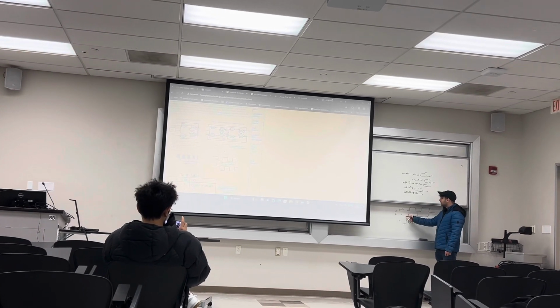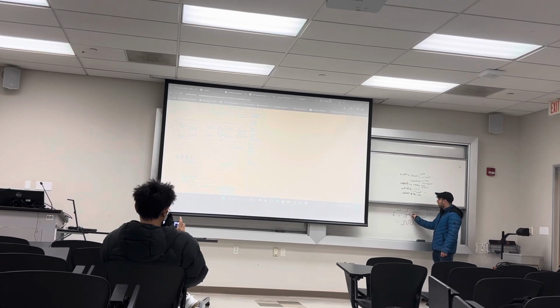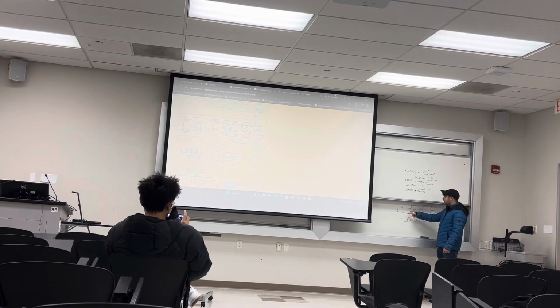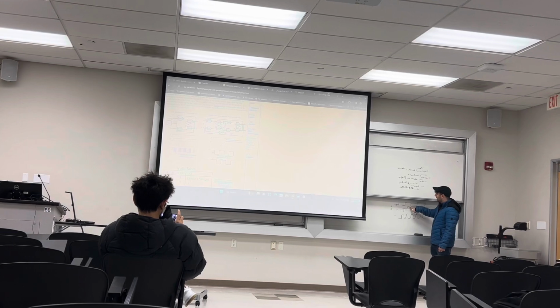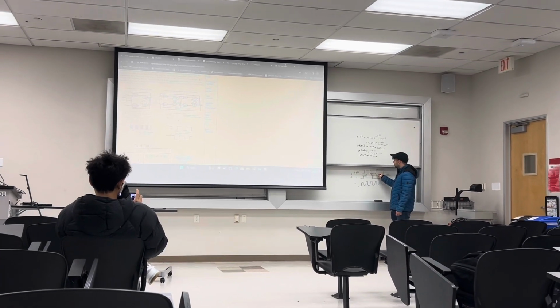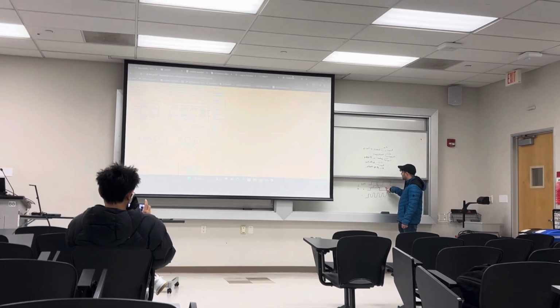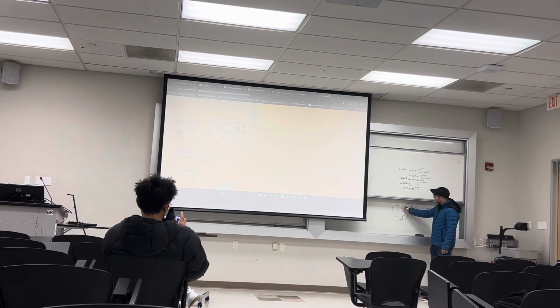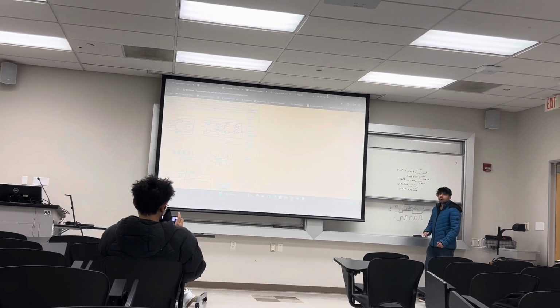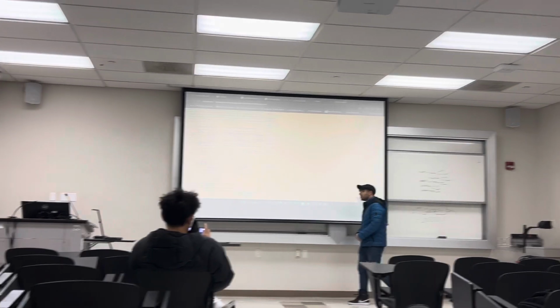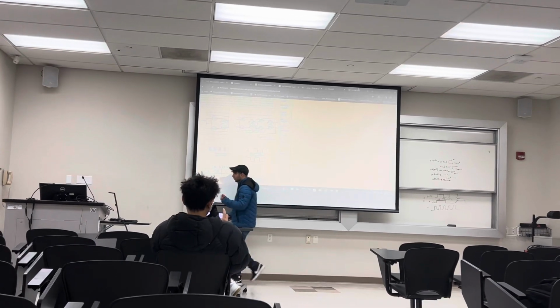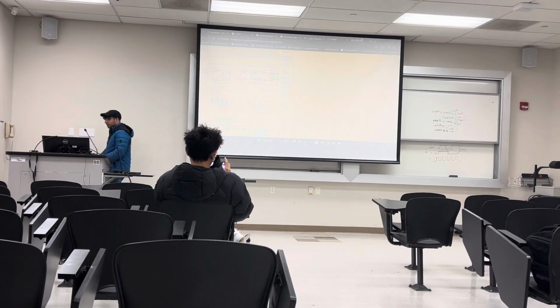Or you can put K the same as J with a delay. When you put a V pulse, it asks you for a delay time, so you can also do something like this. These are the ways you can set the V pulse. So put some numbers on the pulse width and periods, and then check the conditions.